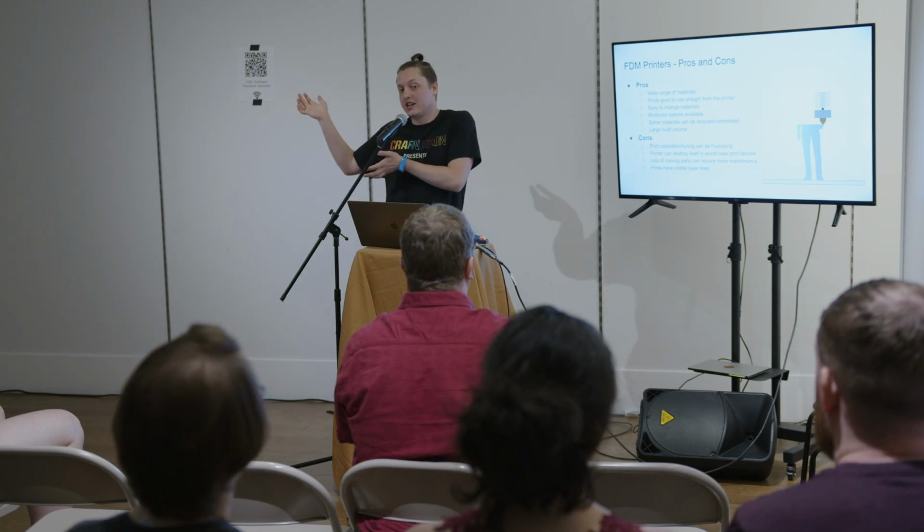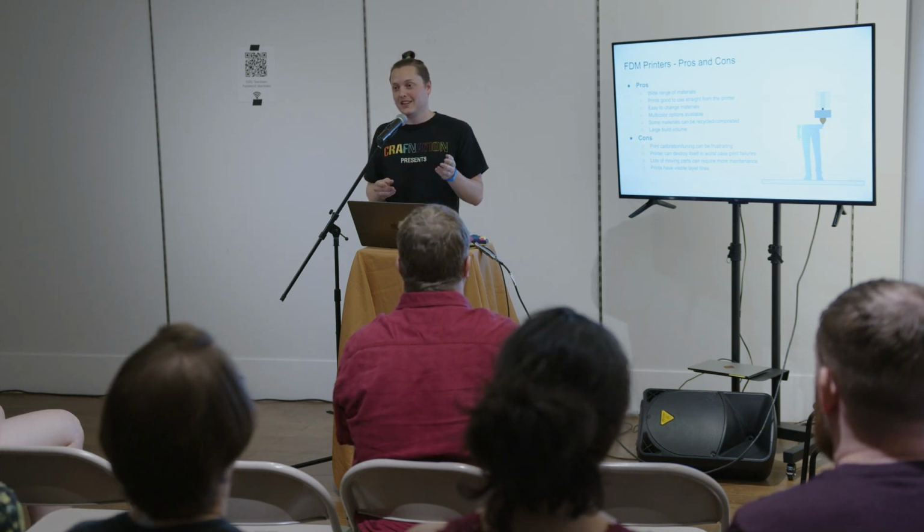There are multicolor options. Some printers have a unit that allows them to print in multiple colors. You can see we have the Bambu X1C just right over there in the 3D printing area, and that's capable of doing multiple colors. It does increase print time whenever you have multiple colors because it has to take the time to purge out filament. If you go from black to white, black really overpowers white in a color, and so you really have to purge a lot of filament to get that to be a pure white again.